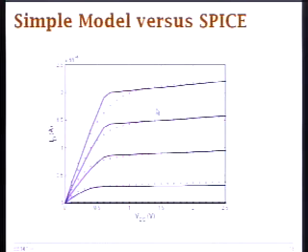For example, when you estimate your threshold voltage, you need to make sure that you pick the right points. Where is the threshold most important? If you're given a current formula from your model, are you going to estimate your threshold based on the values somewhere over here, or maybe in saturation, or in linear mode, and why? That's what you have to explain with that question.